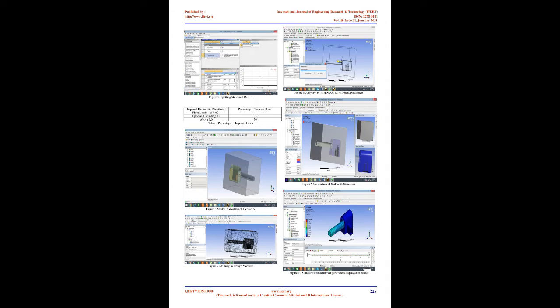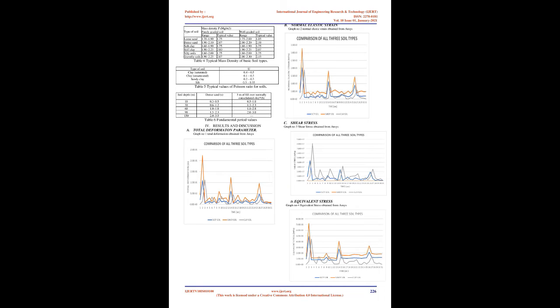Also, the soil structure interaction, SSI, problem has become an important feature of structural engineering with the advent of massive constructions on soft soils such as nuclear power plants, concrete and earth dams. Buildings, bridges, tunnels and military structures may also require particular attention to be given to the problems of SSI. If a lightweight flexible structure is built on a very stiff rock foundation, a valid assumption is that the input motion at the base of the structure is the same as the free field earthquake motion.